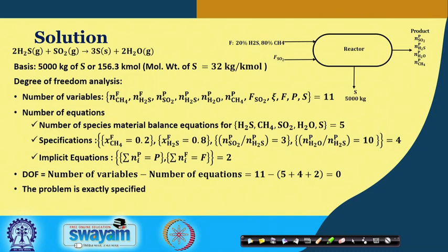So initially, whenever you are doing such kind of problems, it is advisable that you go through these degrees of freedom analysis, and as you gain expertise, then perhaps you may not do this particular step in solving your problem. So let us first see how to do this degrees of freedom analysis. Here, first we count the number of variables involved in this particular system.